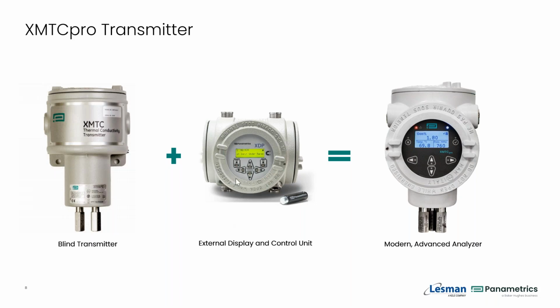an improved display package that accepted that 4 to 20, powered the transmitter, and then was able to send whatever signal you needed back to your PLC or your DCS. Again, a 4 to 20. And that was programmable. You could get to most of your parameters right from that display package. But that required two pieces, a blind transmitter and an external display.